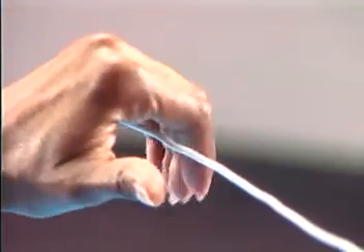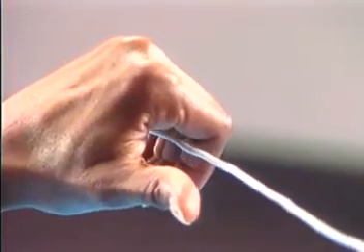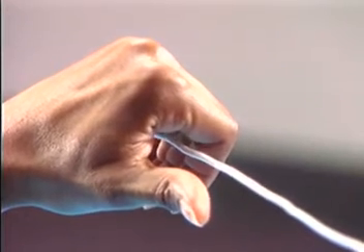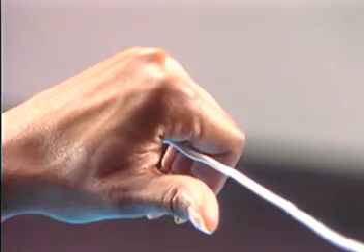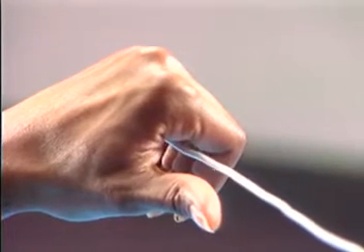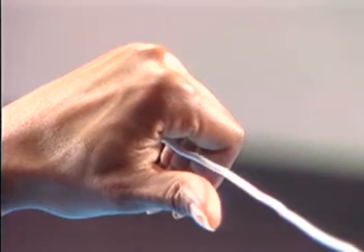The direction of this circular magnetic field around the conductor is important for the operation of generators and motors. Here's a simple way to determine its direction. This length of insulated wire will be used to demonstrate. Curl the fingers of your left hand as if you're grasping the insulated conductor. Make sure that your thumb is pointing in the direction of the electron current flow. In this position, your fingers will automatically be pointing in the direction of the magnetic lines of force around the conductor. This is called the left-hand rule for conductors.